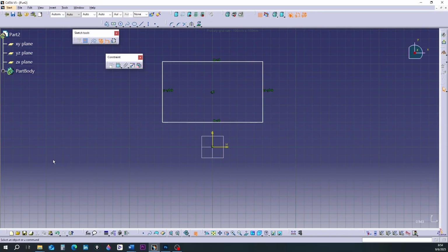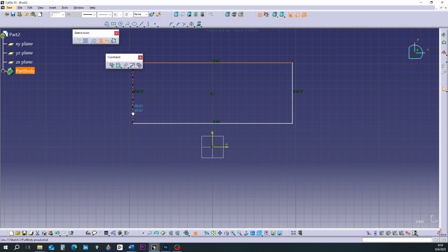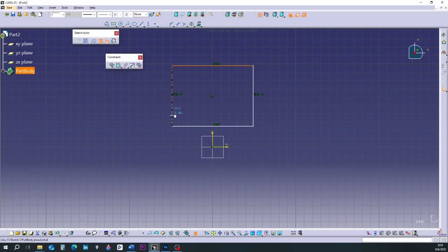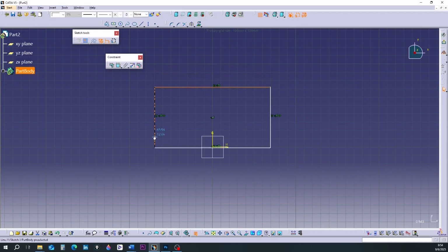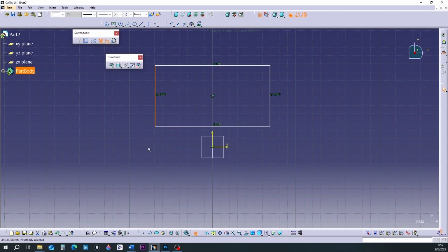Move the mouse pointer over one of the vertical sides. The mouse pointer changes to a hand. Click on the vertical side. The pointer changes to a fist. While holding down the mouse button, move the mouse horizontally. It is seen that the opposite side also moves proportionally. The amount of movement of two sides is such that the vertical axis is always in their middle.